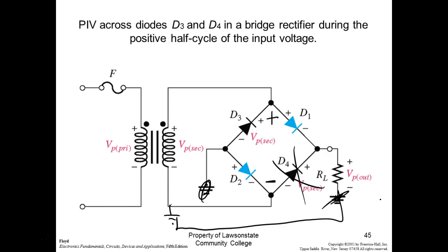This is a 1 amp transformer. So it would put out approximately 12.6 volts at 1 amp if you load it with 1 amp. We're using a 100K ohm resistor, so we're not loading it at all. Let me change it over to, so I got a brown, black, orange.